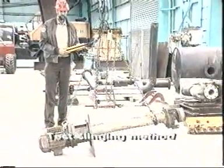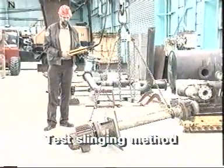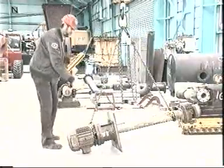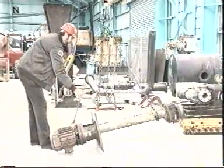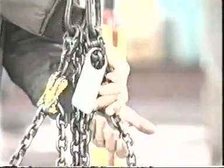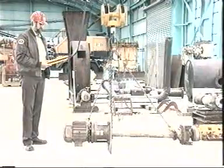Checks must also be made to see that the load is correctly slung. If the weight of the load is not evenly distributed, then the load should be lowered and the slings reconfigured or other corrective action taken. Take the time to check that the lifting equipment is functioning properly.